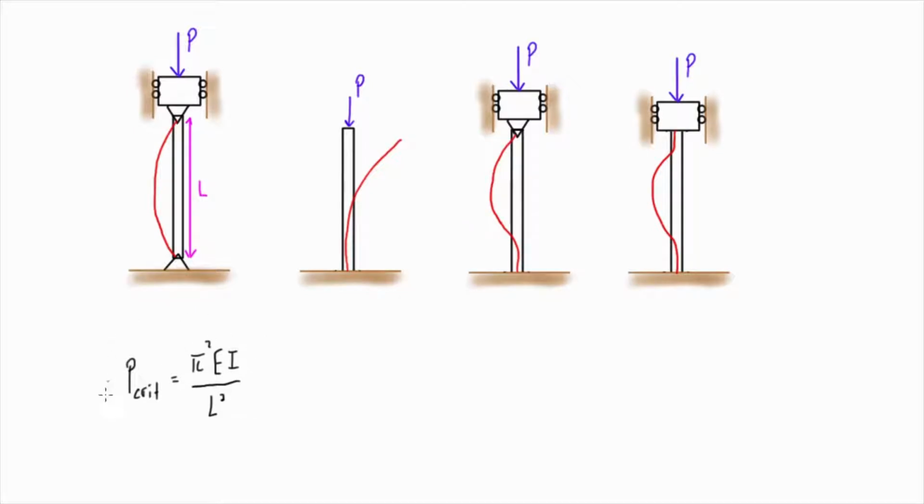So what we should really be writing this equation with is a subscript E, saying this is the effective length. Now in the case of the pin-pin connection, our length is equal to the effective length, and that's why this expression doesn't change at all whether we're talking about effective length or just length, because it's the same when we have double pin.